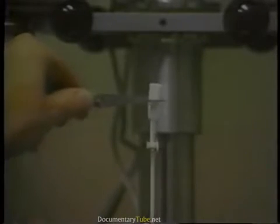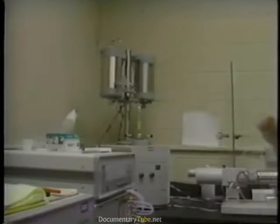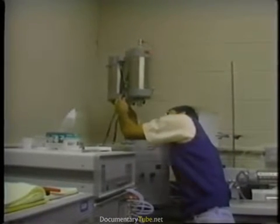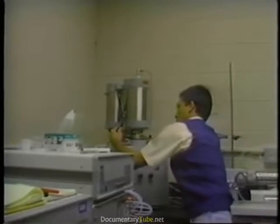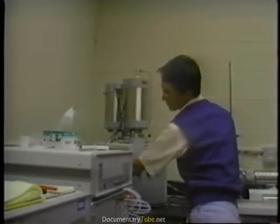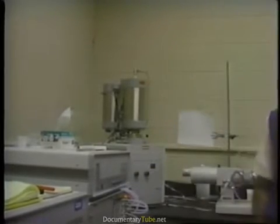Researchers often need to know what portion of the cement has hydrated. The degree of hydration can be estimated by heating a sample of cement paste and measuring weight loss as a function of temperature using thermogravimetric analysis equipment. The free water in a sample is driven out by heating to 105 degrees Celsius. At 105 degrees, the sample is dry, but still retains its strength.